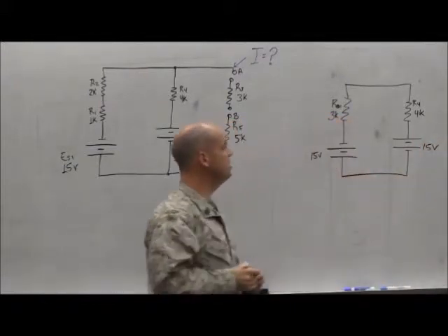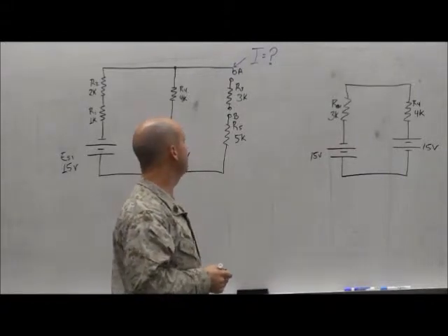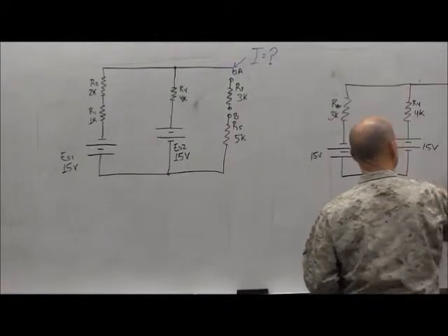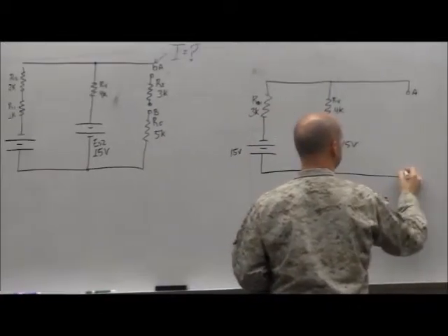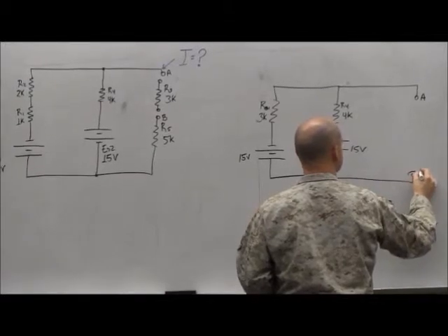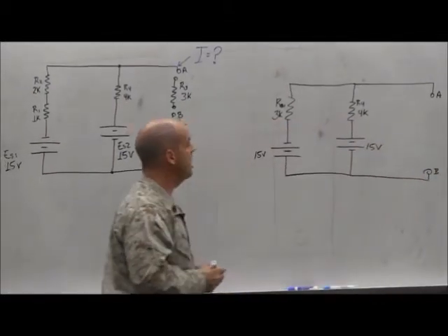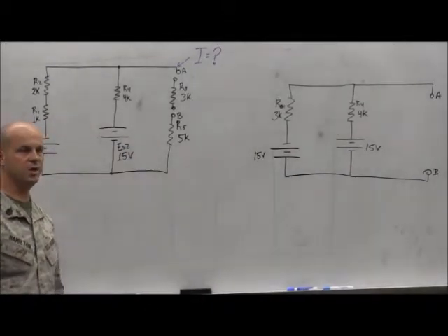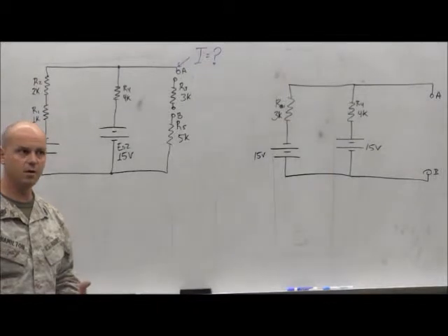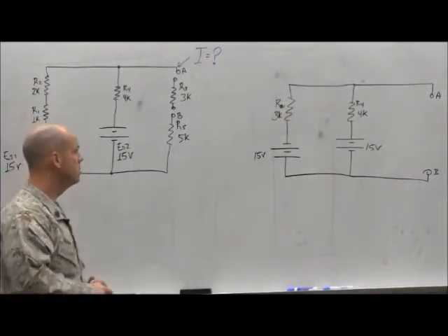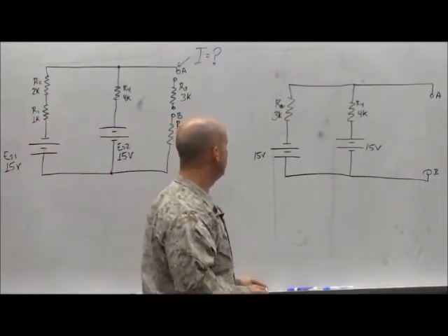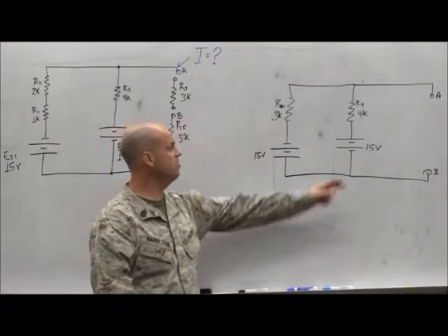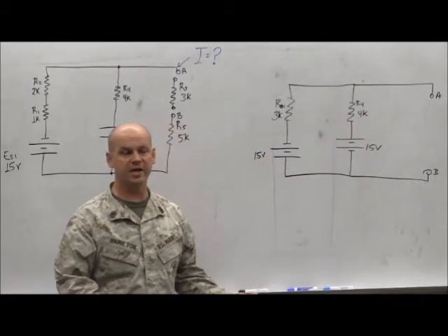So that's basically what I'm dealing with there, right? With one exception. I've got to put in my A and B. For all intents and purposes, that would be A and B, would it not? Sure, there'd be an R5 in there, but R5 doesn't get any current, so it's not going to factor into voltage Thevenin. Okay. Do I even need to find a voltage drop for that REQ1? No. If I just find the voltage drop for R4, that's more than enough. That gets me from A to B.